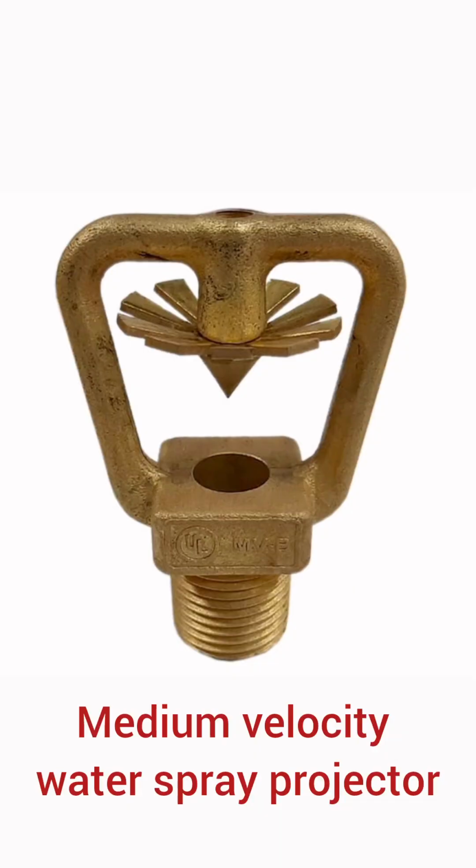Water spray systems are basically of two types, which are fitted as fixed installations. The high velocity water spray system is used to fight the fire in oil, and the medium velocity water spray system is used to provide protection for the plant and equipment and to prevent explosions. The equipment is equally suitable for indoor or outdoor use because the pipe work can be so designed that no water enters the installation until the fire is detected. The risk of water freezing in the pipe work is therefore eliminated.